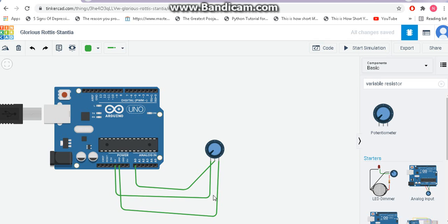See, 5 voltage side. So if I rotate this way, my arrow side, that means clockwise, it will slowly decrease, and when it is at the rightmost point, I mean when I press this point, the analog value is going to be 0 because 0 voltage will be there at point B. Then if I rotate anti-clockwise, again the analog values will be increasing, and at the leftmost point here it will be 1023. So this is 5 voltage, this is 0 voltage, clear and obvious, right?